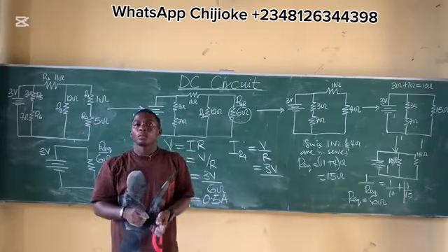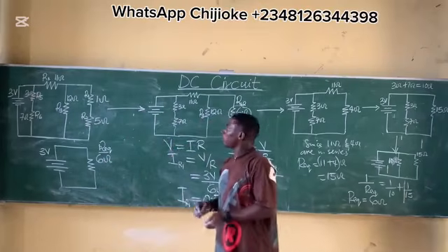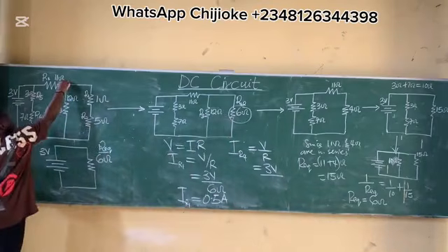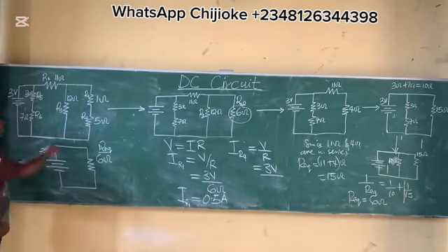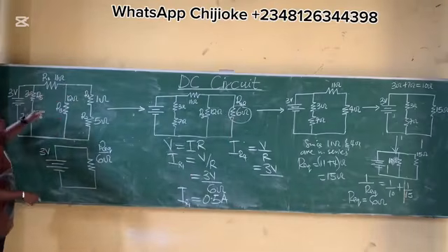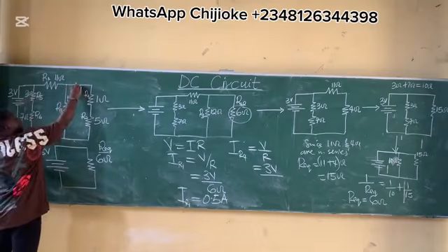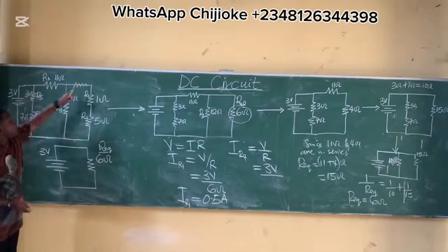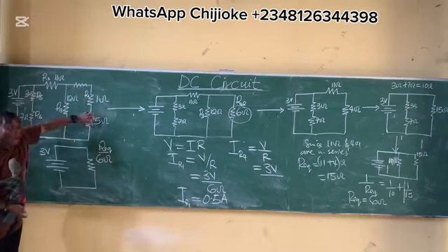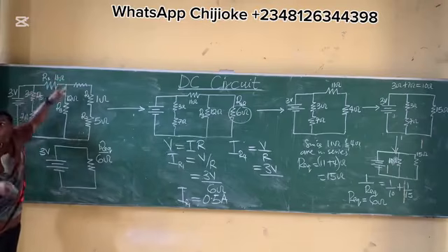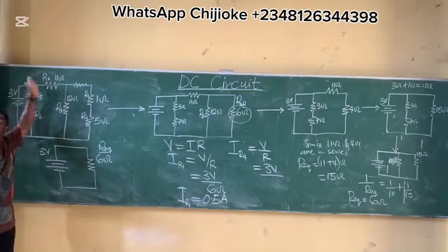Yes, ask. The resistor for R1, is it not going to series with R2? Is it not? No, because there is R3 in between. It is only when this 11 ohms is somewhere here. If this 11 ohms is here, like this, you now say 11 ohms, 1 ohm, and 5 ohms are in series. But this terminal cuts it to be in the second section.